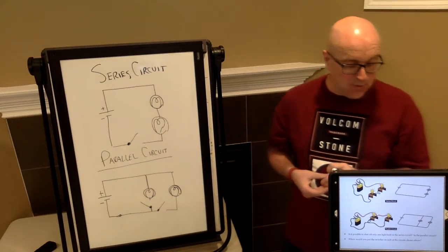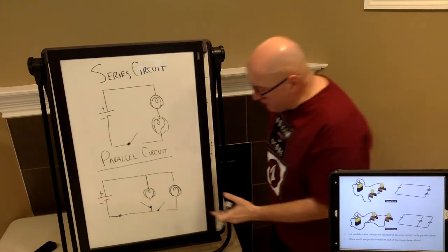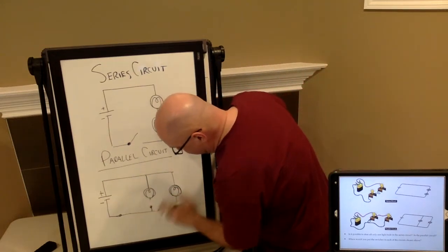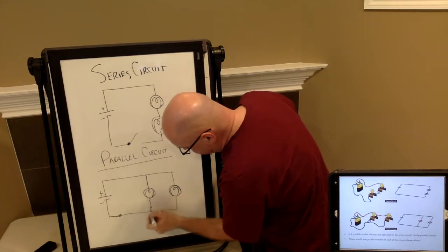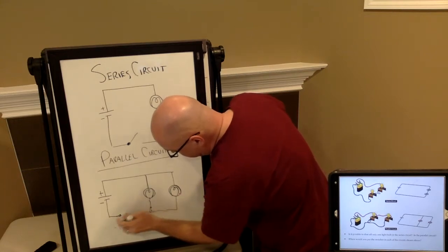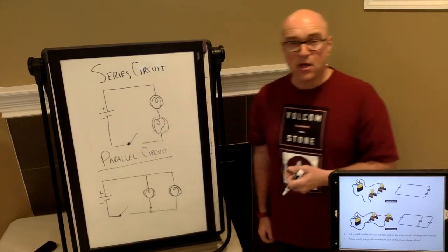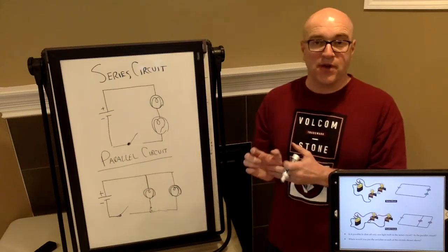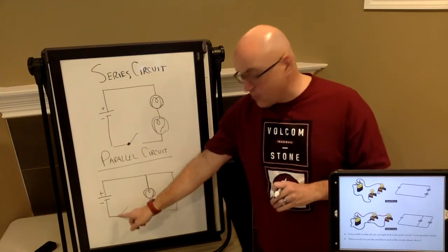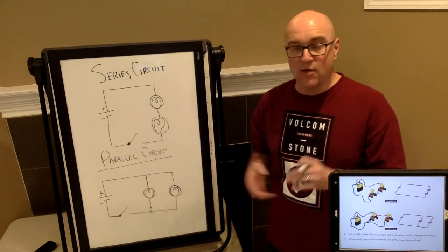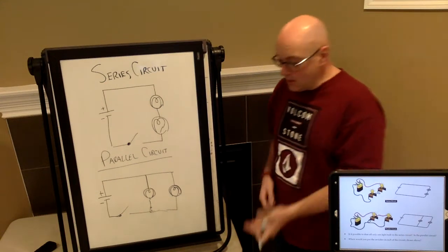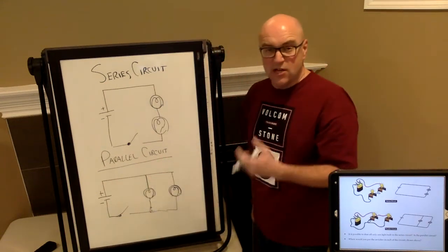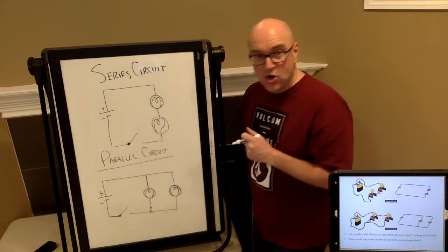And again, where would you put the switches? It all depends on where you put your switch. If I just have a switch over there, then this parallel circuit functions like a series circuit. If I kill the switch here, then all my lights on the circuit will die, right? Because the electrons are basically disrupted no matter which path they're going to.